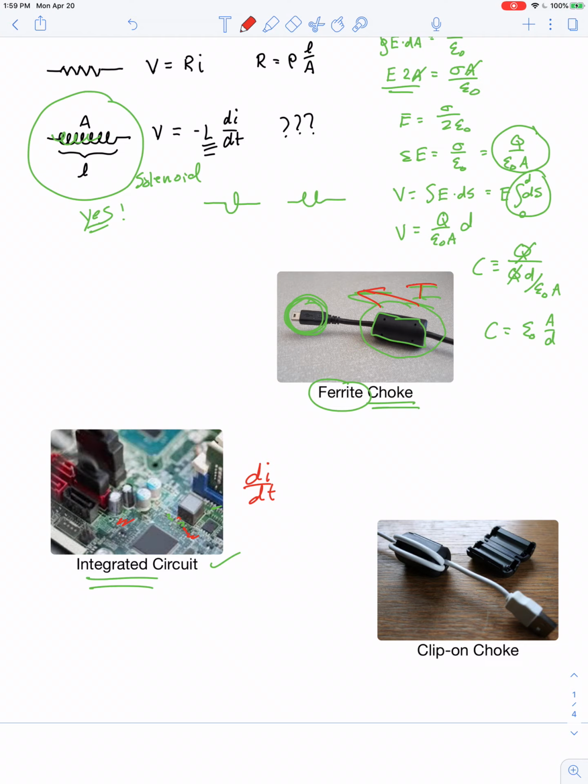There's not just a value of I, but what if you get a surge in the current so that there's a value of di/dt? Then that rapidly changing current can cause thermal expansions on these very delicate wirings, which would be no good. It can also, according to our equation for voltage, if di/dt is really large, there can be a big back EMF, and that can create arcing across small components of the integrated circuit. So needless to say, we want to try to eliminate any values of di/dt.